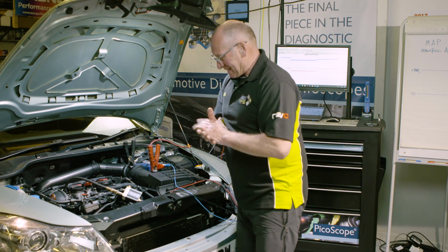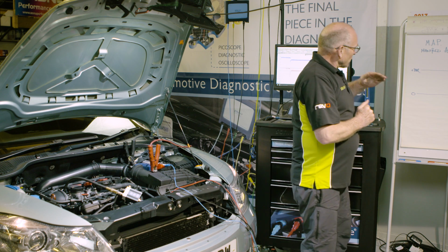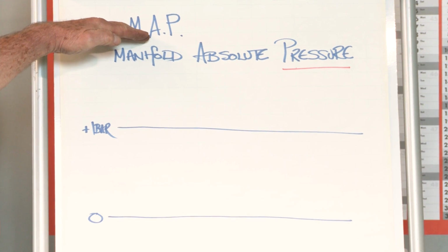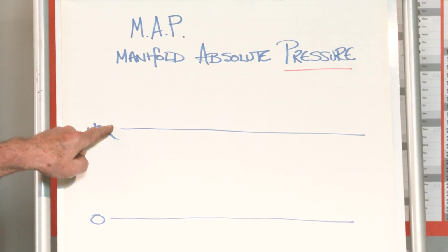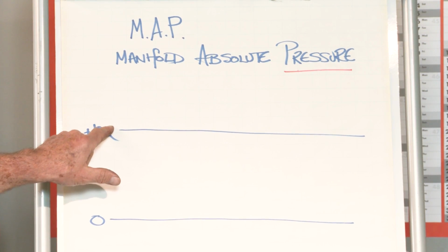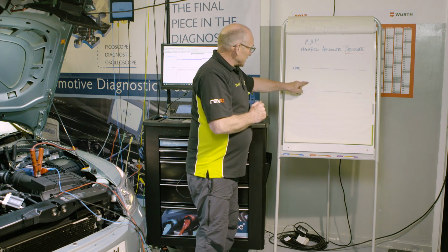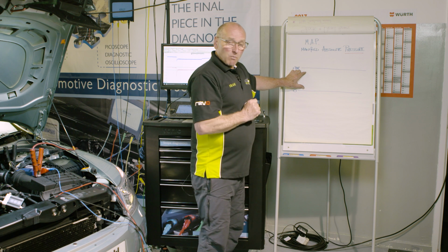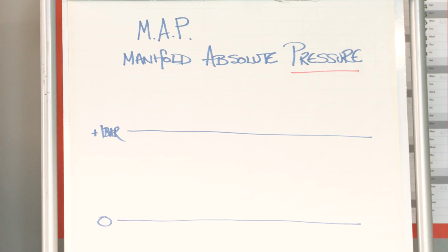real-time pressure. Now, let's go back to this flip chart, please, just for a moment. When you use a compression gauge, you only see half of the evidence, the positive pressure above 1 bar. You do not see the pressure differential, pressure, not suction, not vacuum. You do not see the pressure down here. I've removed the one-way valve from the compression adapter, so we're going to see total pressure in the cylinder in real time when the engine runs.